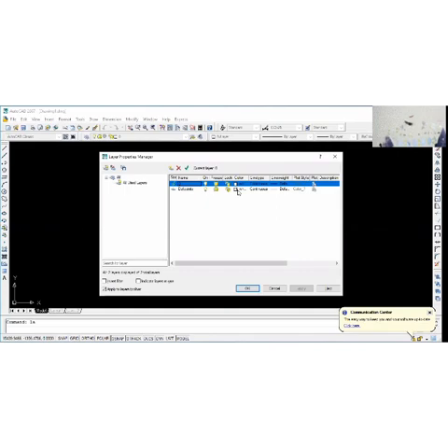Now your layer is very important in AutoCAD because it helps to organize drawings. For instance, in this place, you have new layer. It means you can create a new layer. Here you have delete. It means you can delete a layer. And then here you have set current. It means you can make a particular layer current.